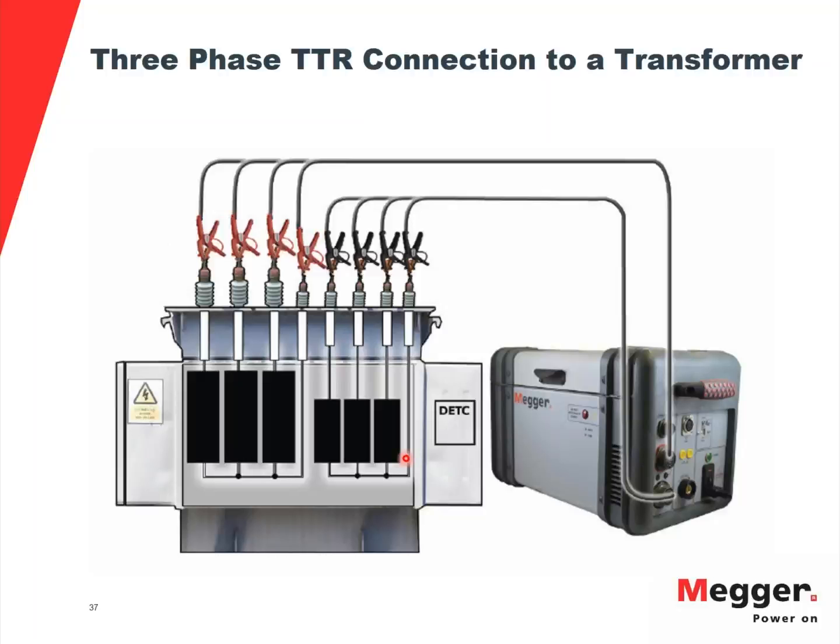In addition to that, you may have a tap changer on those auto transformers. And sometimes I've seen that, I will try to explain it a little bit in depth. So typically your tap changer has plus minus 10% voltage regulation. And if you think about 33 tap positions, which would give you 0.58% of voltage regulation for each tap transition.